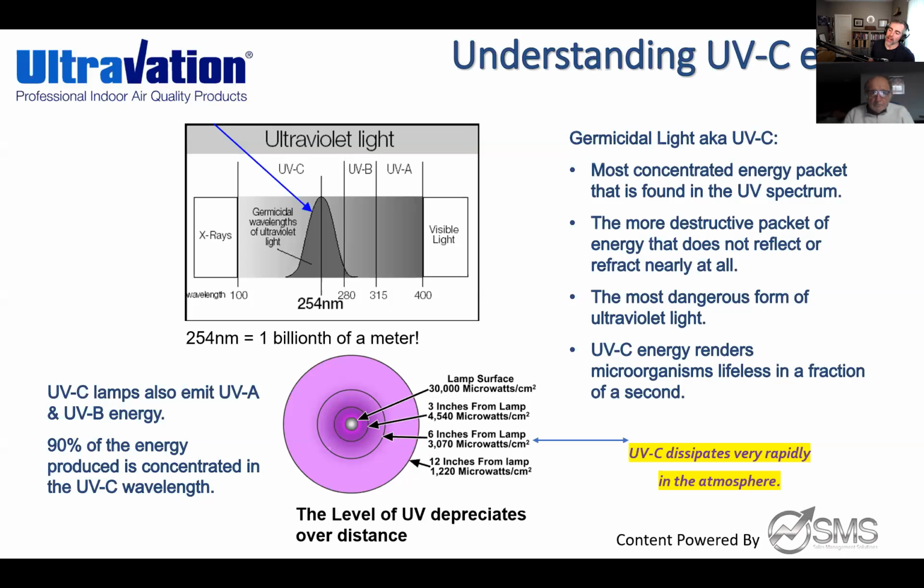Another big clarification is that there are all different kinds of UV light. There's UV light that comes from the sun, and there's UV light that comes from tanning beds and tanning salons. They're not all created equal. There are different wavelengths. If you were installing UV in an HVAC system, it needs to be the UVC class of light, not UVA, not UVB.